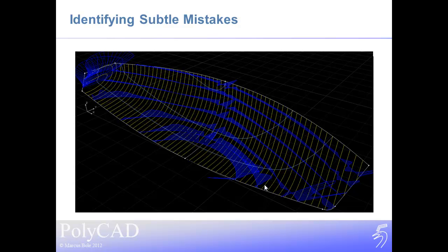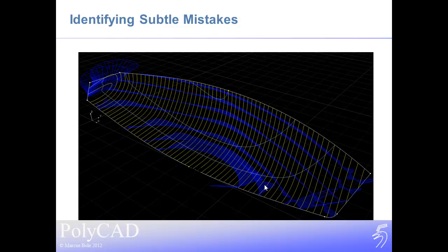So what we need to do is change that midship section area curve so that it has the same definition as our sections. In this case, it's quite an easy one to resolve: we can just remove that curve from the definition so that it affects some of the other definition curves, but it doesn't directly contribute to the loft. And now we get a much smoother shape in our surface.